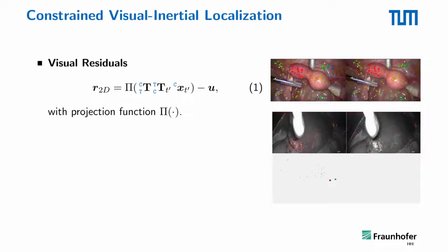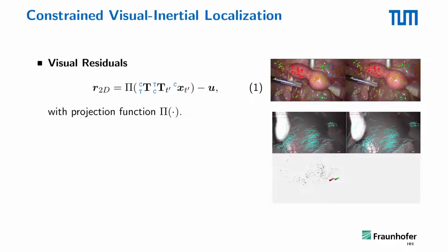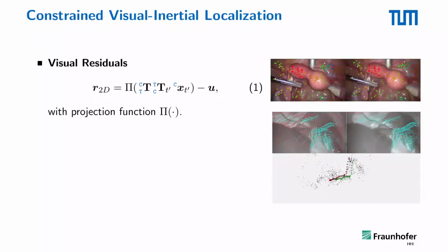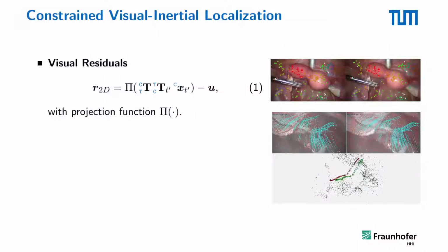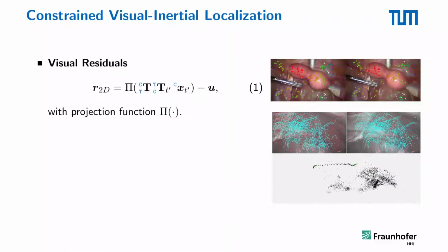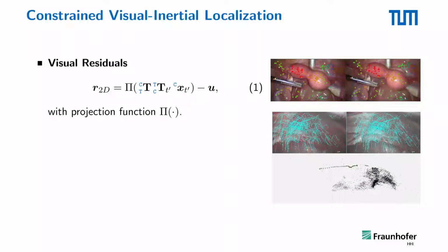At detection time T', we triangulate stereo matches that fulfill the epipolar geometry. The reconstructed points are inserted into a 3D map that is attached to the detection frame. Matches in the 2D image plane, here denoted U, are found in the consecutive frames. The camera movement is then reconstructed by finding a set of points that fulfill the epipolar equation. This is a typical visual odometry approach.